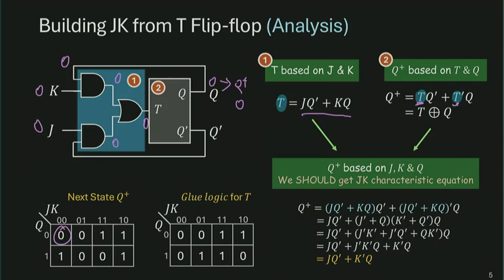Right. Remember, with a combinational circuit, these are also the 2 ways we can analyze it. We can run simulation, putting down some 0s and 1s at the inputs and see what we get at the output. Or we can try to write it out as a Boolean expression and then simplify it. So both of these ways should give you the same description of next state in terms of primary inputs and current state.